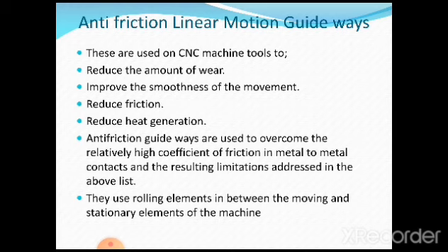A high load carrying capacity is possible by using the LM guideways, to achieve high traverse speed. This is one of the basic advantages or necessities of using LM guideways. So what does traverse speed mean? The speed at which the linear movement is made to move the moving element is very quick and without any stick slip. That is why the traverse speed achievable is more. So thereby it is possible to carry out machining operations at ease without much difficulty, easily assembled.